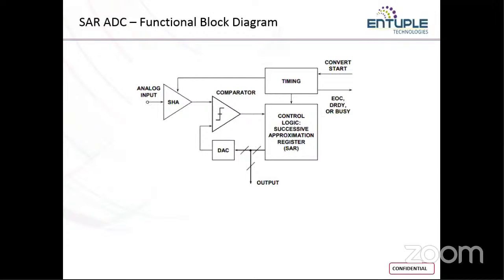Whereas for a comparator, here in Cadence, we made use of an operational amplifier in which the NMOS transistors and PMOS transistors we characterized for a particular value of gain. Here the gain was around 40 dB, I guess. I don't remember. And when it comes to ORCAD PSpice, we made use of LM324, which was an operational amplifier IC that was available readily in the library.